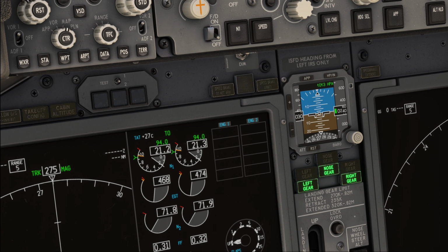Now, when the light is blinking, it shows that there is a condition of more or less than the commanded thrust. The entire block will blink for 10 seconds and then the alert only is going to remain steady until the condition no longer exists. So let's say, for example, that you're adding thrust over here and the engine does not respond appropriately, but it goes to a different thrust setting for whatever reason.